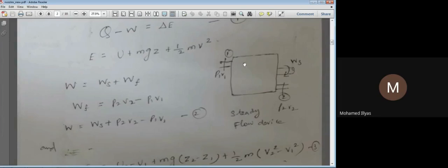In this, the pressure, temperature and other parameters will be constant for a particular period of time at any point. For example, this point. If steam is allowed to expand in a turbine, a high pressure, high temperature steam, for example at around 80 bar and 500 degrees Celsius here, and then it is allowed to expand, the temperature and pressure may reduce at this point, maybe coming to around 60 bar and 400 degrees Celsius.